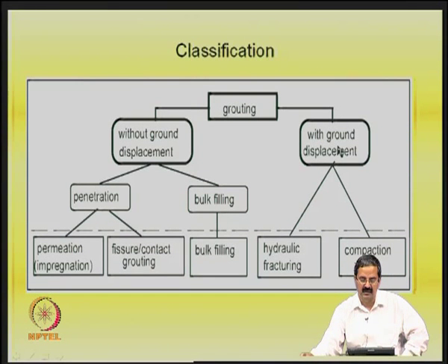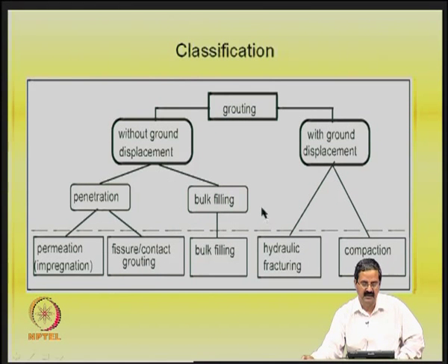Otherwise, one is with ground displacement, the other is without displacement, and without ground displacement, it can again be classified into just penetration, where there is some void and the grout penetrates that area and fills it up. Then there is bulk filling, where if there is a big cavity underground, you can use the grout to fill up that particular space.